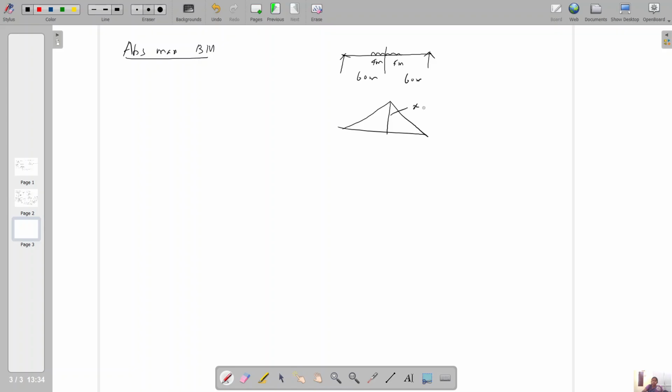We have the formula x into L minus x by L. If you put x equal to L by 2 because of the midpoint, I will have L by 4 as my answer. So L by 4, 120 by 4 equal to 30. And mark at center point, it is 30.